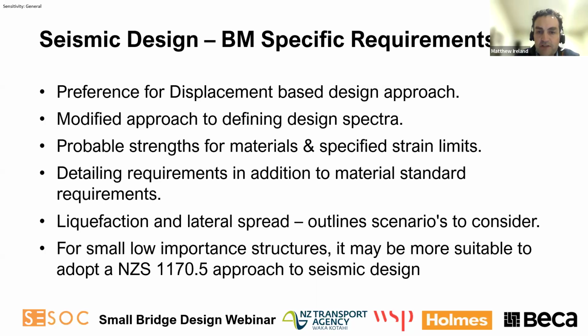Also with bridges, soil structure interaction is quite often a fundamental consideration. So within Chapter 6 of the bridge manual, where you're considering liquefaction and lateral spread, there's a series of scenarios which are outlined that you need to consider related to inertia with liquefaction and lateral spread.